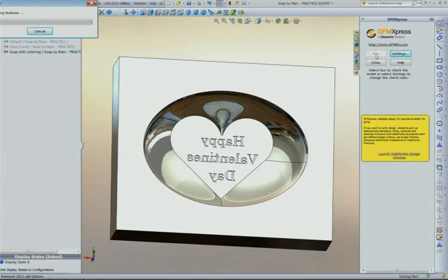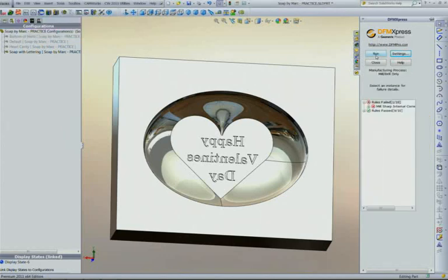So again, like Mark said, DFM Express comes with every SolidWorks package, and there's actually an area in here where you can set up some options. For manufacturing practices, there are rules that it checks for, like the depth of the hole to the diameter of the hole, or sharp corners, things like that. All those things can be set up, and you can set up your own manufacturing rules. If I violate these rules, let me know where I'm violating these rules in my part.